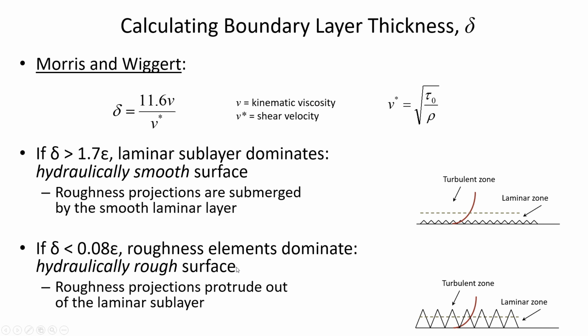So there's a big middle zone where it's neither hydraulically smooth nor hydraulically rough. And we'll get into the implications of that with our empirical equations for estimating the friction factor f. But this is just laying the groundwork so conceptually you can think about that there is a zone in the pipe where conditions are laminar, even if in most of the pipe conditions are turbulent.